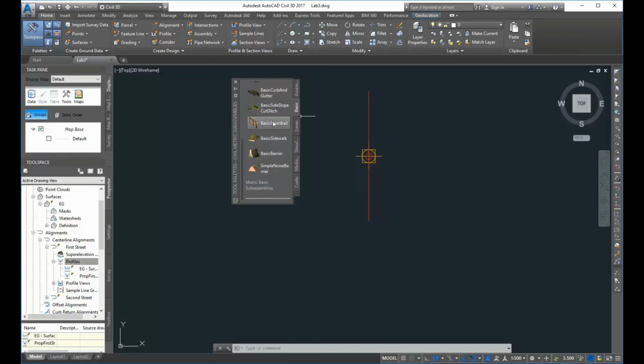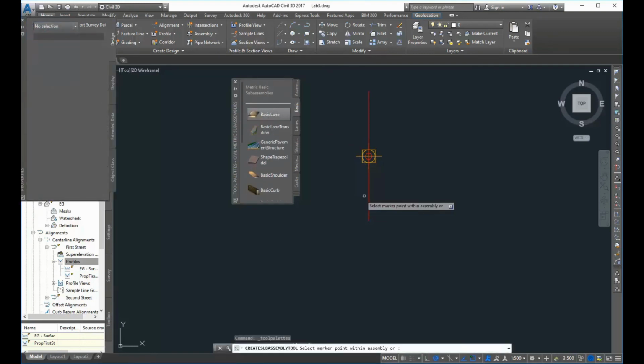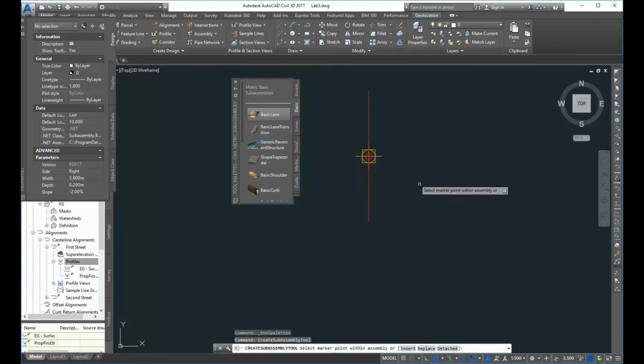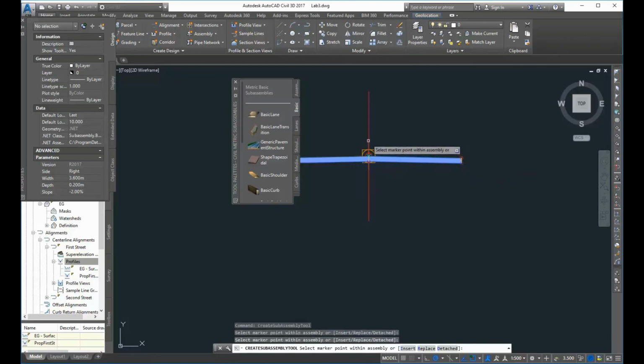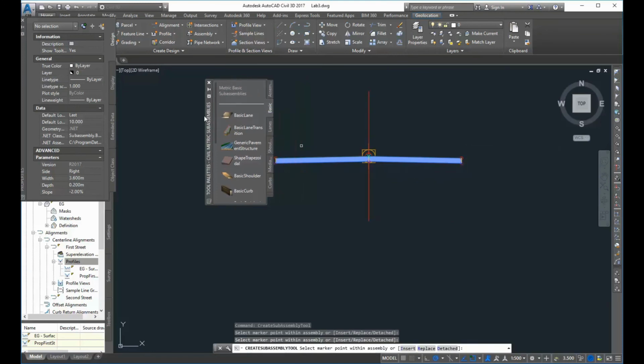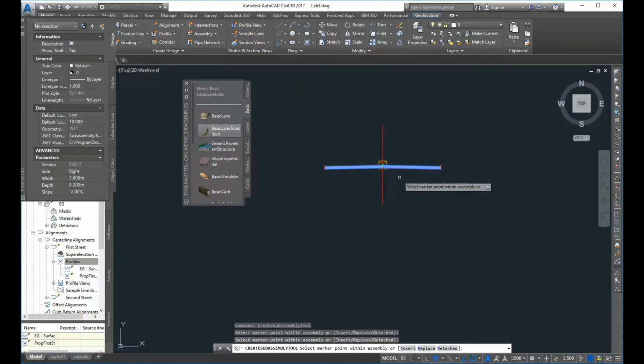So the first thing I'm going to do is select a basic lane. I guess I'm supposed to think like an artist. This is a palette. I've picked up this color, and if I click it, it's going to build in a lane. If I click it again, it's going to build a lane on the other side. So it tends to want to have things be symmetrical.